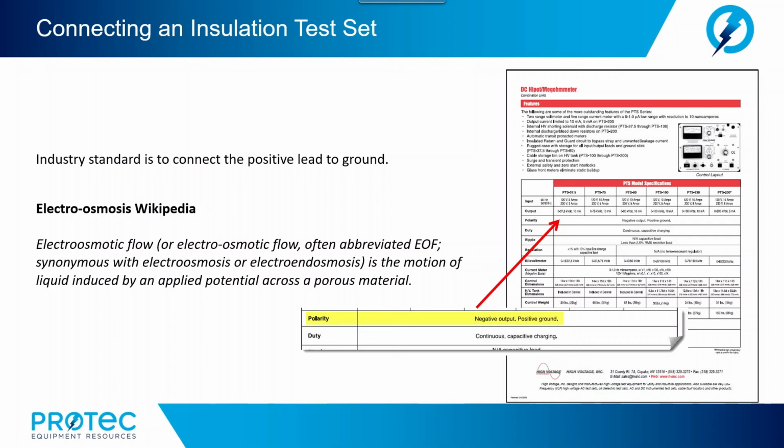The applied potential causes several small currents that flow through and over surfaces of the insulation being tested. The total current is then measured, and the result is displayed as either an ohmic value, or it can be displayed as the actual total current that is flowing. With modern insulating materials, there is little, if any, difference in the reading obtained regardless of which way the terminals of the test set are connected.